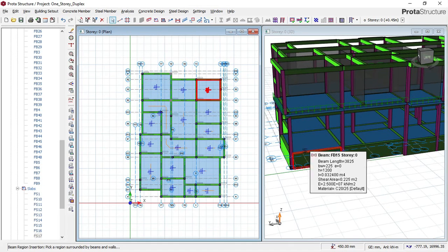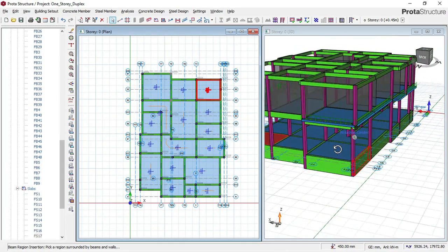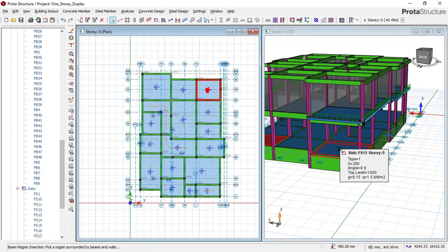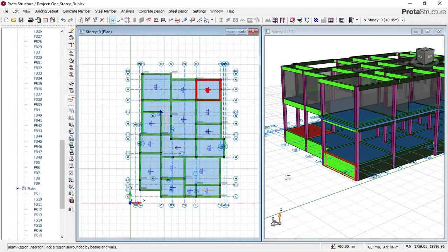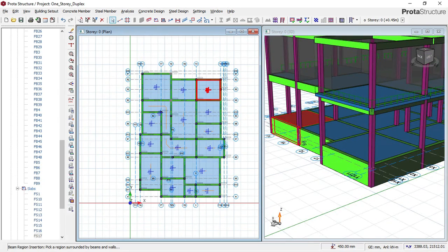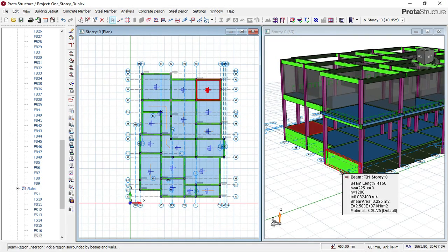That is what they call initial displacement. Over time the soil tends to come back to its normal shape, and when it does, it will cause what they call overburden pressure or active pressure on the edges of the beams. And if this beam does not have a toe, then this beam will be affected.